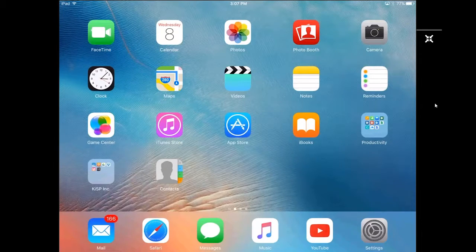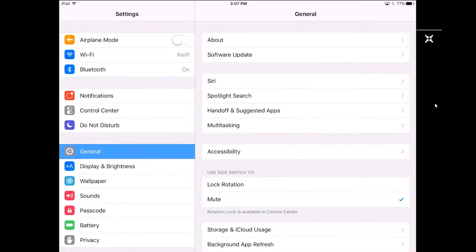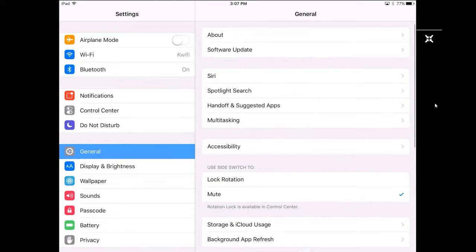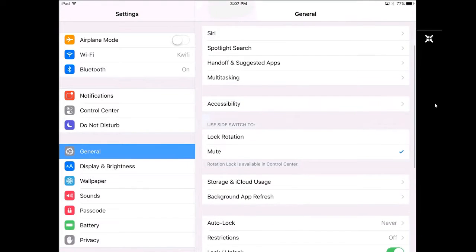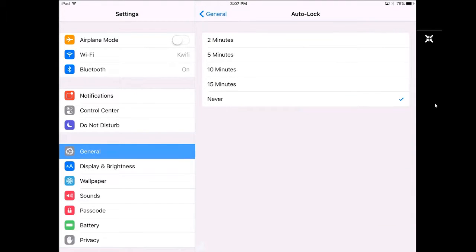But before we start, there are a couple of things you have to make sure that you do before using Kits. Make sure you're connected to a strong and stable Wi-Fi. So public Wi-Fi's or personal hotspotting won't really cut it when you're syncing to our cloud. However, when you're sending emails to your client through the Kits app, it will work. Also, make sure you set your iPad's auto lock function to never or delay as long as possible during your syncing process to ensure a complete sync of your catalogs. So the features in Kits are in-app processes, so you must remain in Kits while syncing.